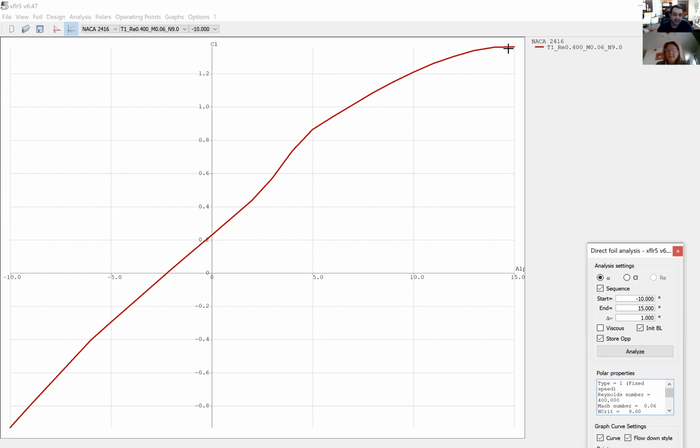Okay. And there is an angle about minus 2.5 that is the intersection between your lift line and your angle of attack axis. This is the alpha CL0, the one where your graph connects with the x-axis, about minus 2.5 on the horizontal axis. So you have 0, you have minus 5, you have minus 10. At the middle of 0 and minus 5, you see here. Okay, here. Exactly. So this is the angle of attack at which your lift is equal to 0. It means that your wing doesn't generate any lift.